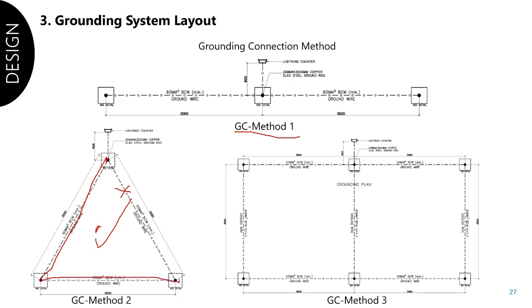If there is a problem at this point, the ground rods are still interconnected. Unlike with number 1, if there's a problem here, it reduces your ground rods, so of course it would increase your ground resistance. That's my main reason. For grid grounding, yes, it's still connected, almost the same as the triad design. If there's a cut, it's still connected with each other.